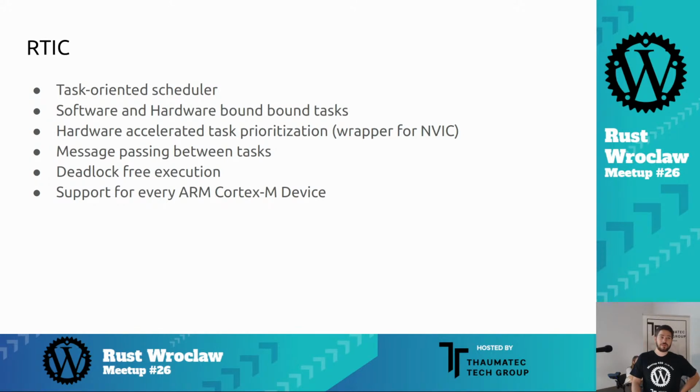And it supports every Cortex-M device, because it is both the strong part and the weak part. It is very tightly bound to the Cortex-M architecture because it uses NVIC, which is the nested vector interrupt controller, to do all the scheduling.